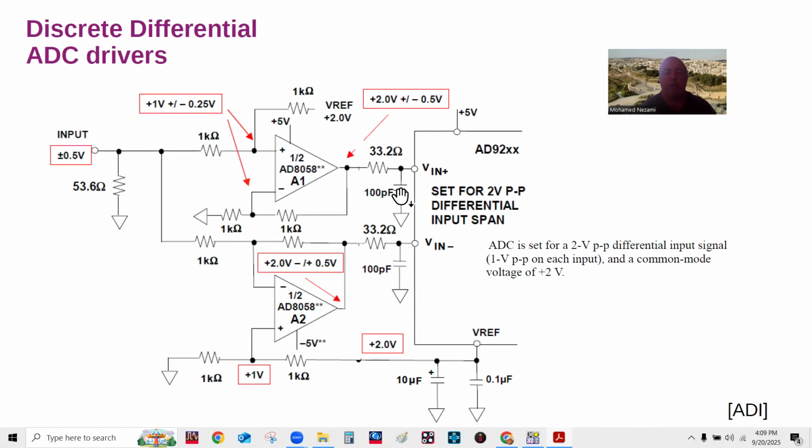Whatever the output comes in here, these are two RC filters, low pass filters. Just ignore these for right now. It has nothing to do with what we are talking about. So we have the signal coming in, and we go into a non-inverting amplifier with a gain of 1. That created, at this point here, a 180 phase shift with the input.